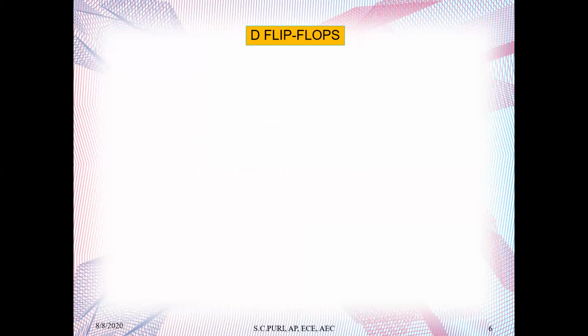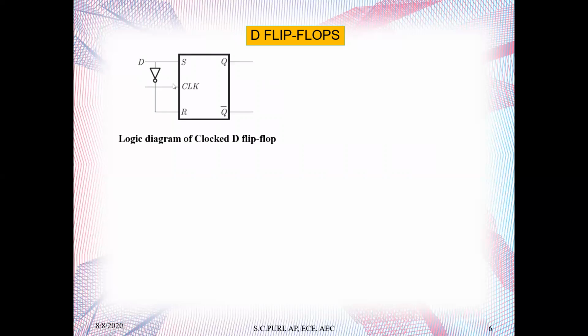Now let us go to the D flip-flop. What does D mean? D means delay. D means delay flip-flop. As you can see here, this is the logic diagram of a clocked D flip-flop. It is a simple logic diagram. This is the logic diagram of an SR flip-flop. In this S, we put input D, and for the other input we put an inverter. When we use this inverter, the 1-1 condition will be avoided.